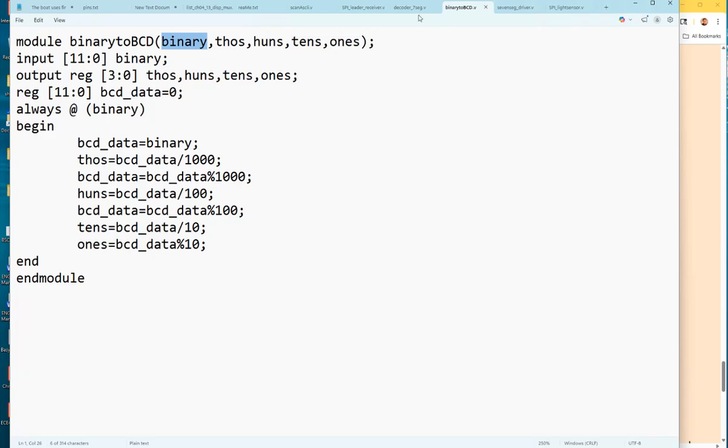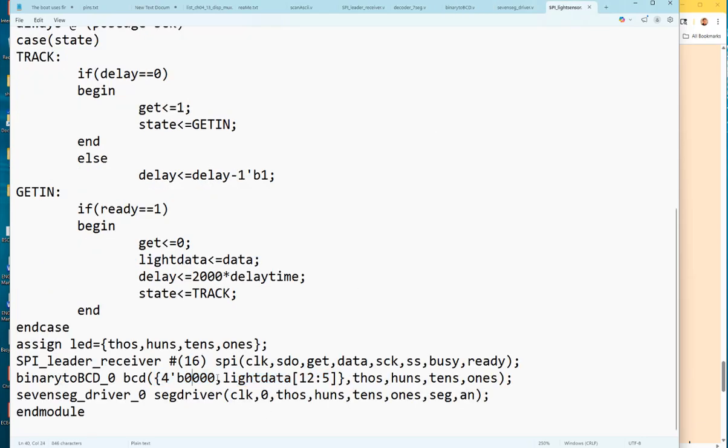So if we come back to the top, basically this guy can be changed to 720, right? It should work. So here, we don't really need 4 leading zeros to be concatenated to your 8-bit data because they're not being used. If you look at the top, they're trying to assemble that 12 bits for your BCD converter. And to do that, they have to put 4 zeros in front of the ADC data, right? It's just so silly, right? We just don't need it. So it's only 8 bits.